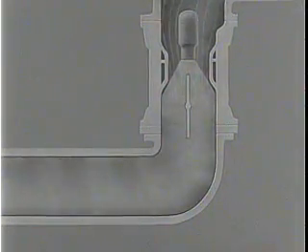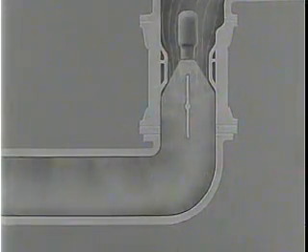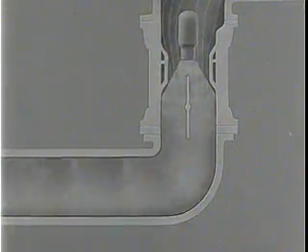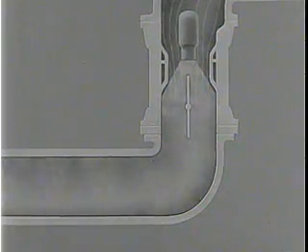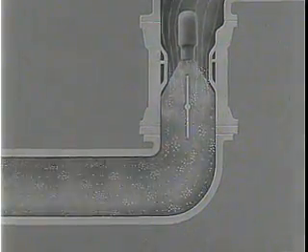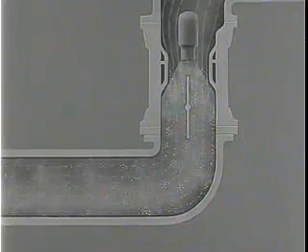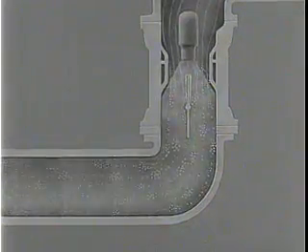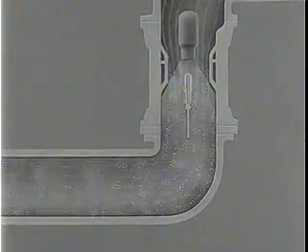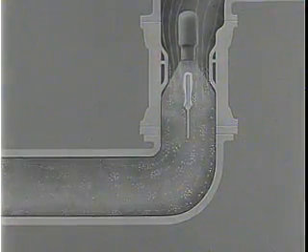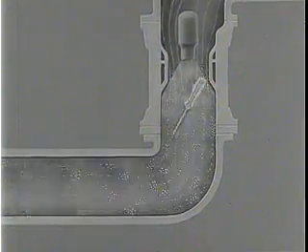When the outside air temperature is at or below freezing, a different icing condition occurs in the carburetor. The temperature inside the carburetor is well below freezing, and there is, in effect, a harmless snowstorm taking place. However, in this situation, ice may still form on the throttle, and it is advisable, whenever structural icing is encountered, to move the throttle occasionally to keep it from sticking.